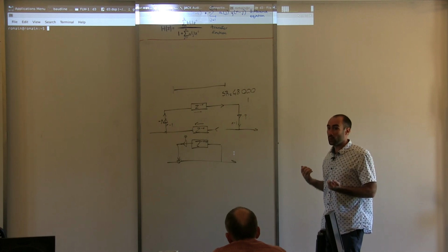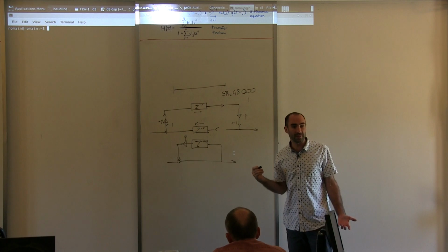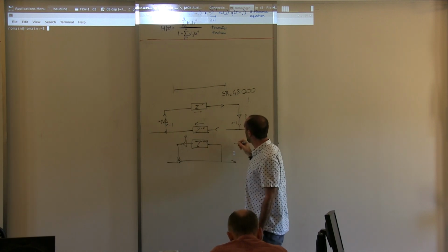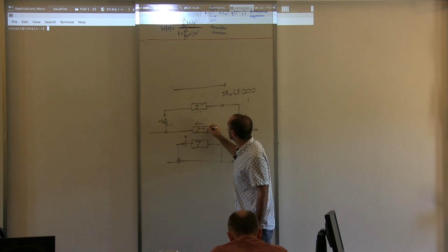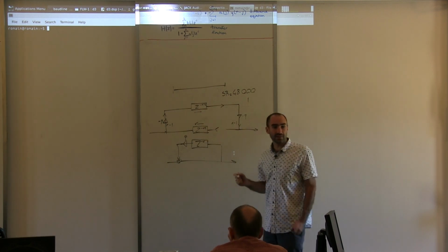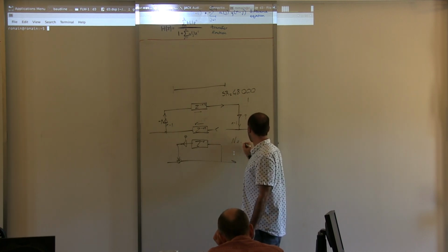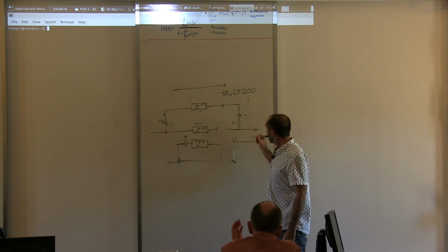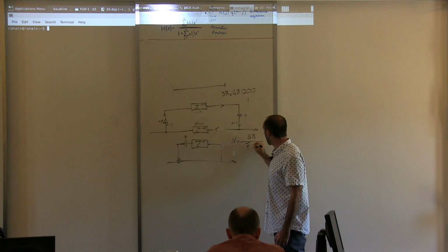Literally. So now we have a way to calculate the frequency of the string as a number of samples. Let's say that what we want to know is n. Here I'm just going to say that this is n over 2, and what we want to know here is n, the length of the delay line. So how am I going to calculate n? n is basically going to be equal to the sampling rate divided by the desired frequency of the string.